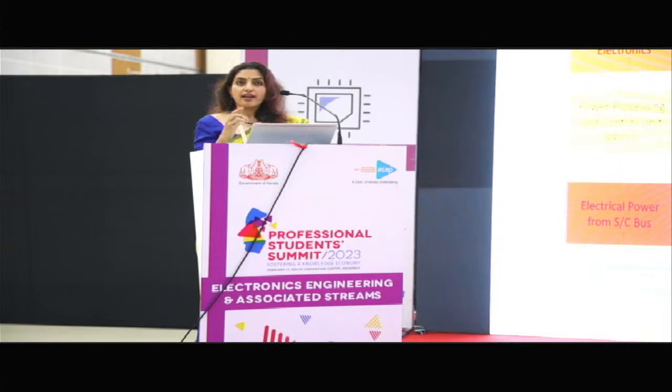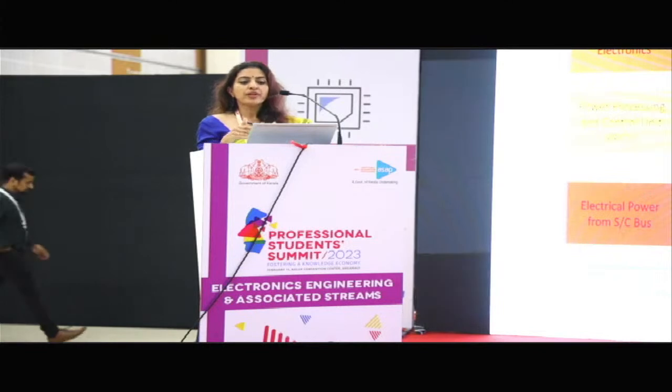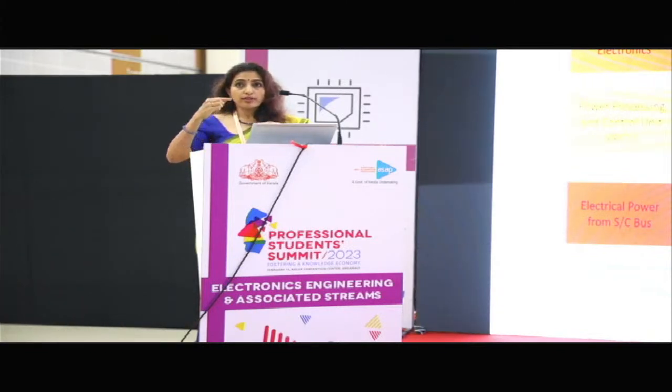Now for that, I already told you we require an inert gas. We are working with xenon, so a xenon storage and feed system is required. And I told you about the heater generation, the voltage generation and all that. So there are different voltage and current requirements for the SPT to work properly. So we have the power processing and control unit, and for it to work, we have the input power from the spacecraft bus. All this will be controlled by a computer, in the control electronics. So the plasma is generated.